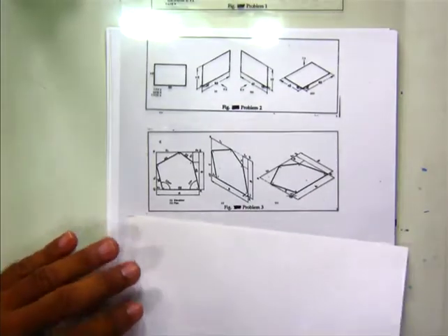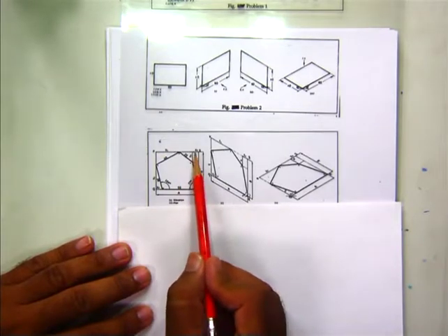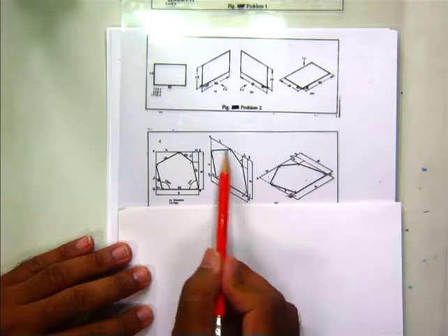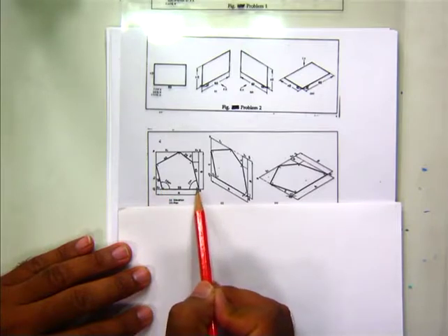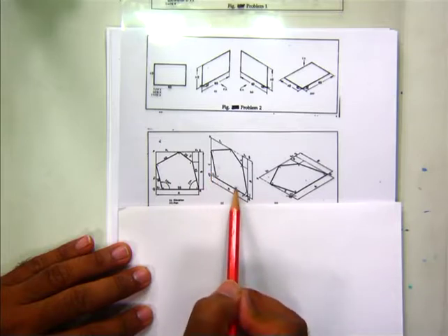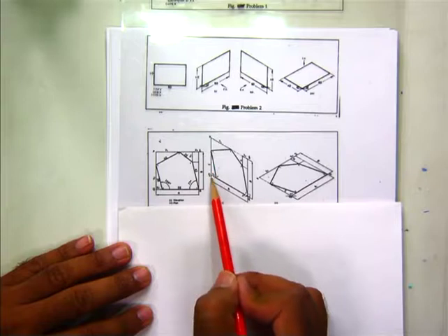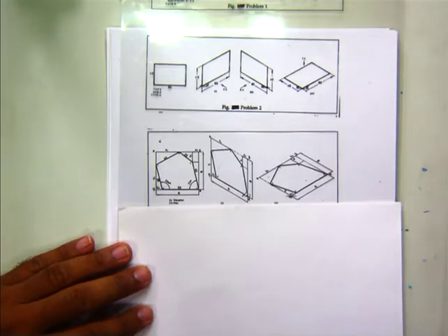Again, if the figure is a circle, pentagon or hexagon, you have to inscribe it in a rectangle. Then you complete the rectangle first, and whatever the actual dimensions of this edge, this edge, this edge and this edge are, you put them in, and then you get the respective views. According to the respective view, you will get the isometric. If it is a top view, the isometric is like this. If it is a front view, the isometric of the given plane would be like this. So friends, this is just to summarize or refresh what we saw in our first lecture, the basics.